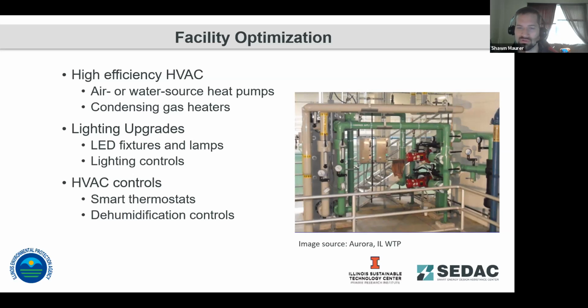These are really, really useful where you've got a facility that has either a large groundwater storage tank on site you can tie a heat loop into, and you've got that massive heat capacity there, or facilities that have a relatively constant flow of water through them. If you've got a smaller facility with on-off controls, where the water flow isn't consistent through the facility, what we may look into there for you is the air source heat pump option instead.